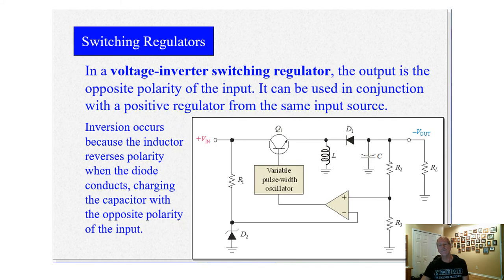And we also have voltage inverters, so you can convert a positive voltage to a negative voltage. And it's very, very common, very handy for audio circuits where you need that negative rail. And this is how it's done in the power supply on your bench, for example, to get plus or minus 12 volts. The inductor reverses polarity, and then here's a catch diode, which, with the switching waveform, causes this capacitor here to charge negatively.